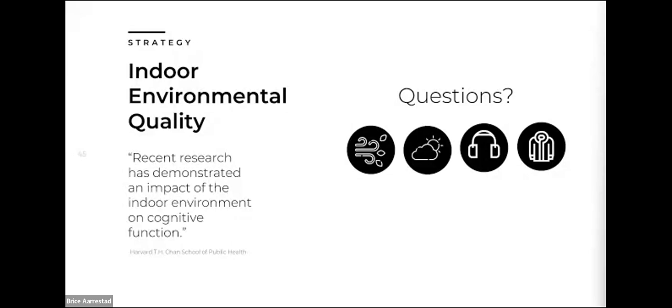All right, so we've talked about two different aspects of designing for health, designing for well-being, through biophilia, through indoor environmental quality. A lot of what this is pointing to is maybe more glass to help with circadian rhythms or to help with connections to nature. But as a designer, you're like, what's that going to do to us from a thermal standpoint? How is our energy use going to change because of this? So there's always a balance, right?